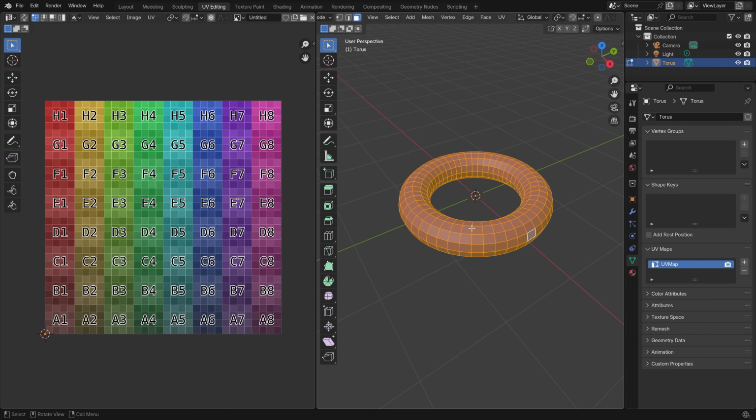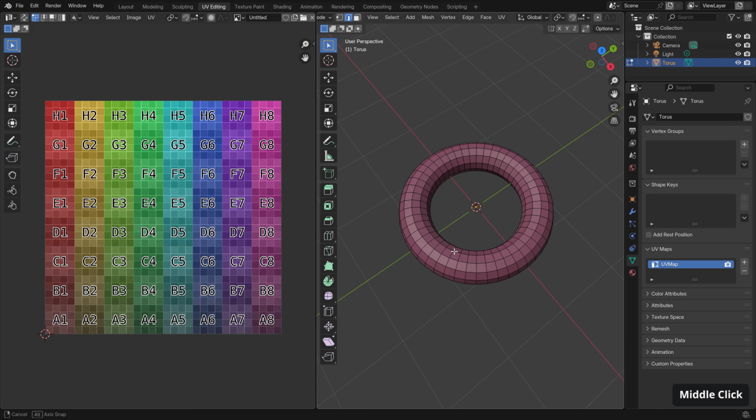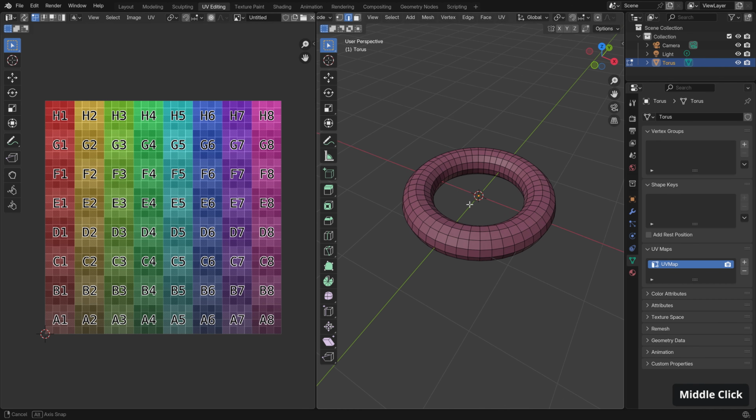Well, basically, if you think about it, this ring is basically an infinite cylinder shape. Now, what do I mean? Well, let's have a closer look. Let's move the camera up a bit here. And as you can see, this is a cylinder that goes all the way around and then connects up to itself again. Now, if you remember with the cylinders, what we need to do is remove the top and bottom part of the cylinder. Since this is connected to itself, we just simply need to add in a cut over here to separate off the ends, as it were.